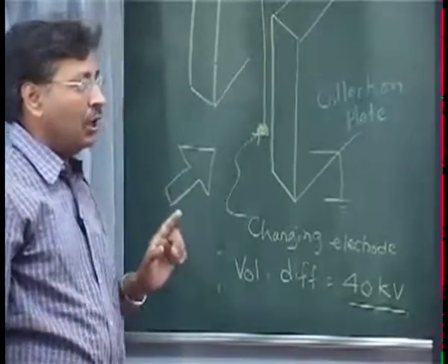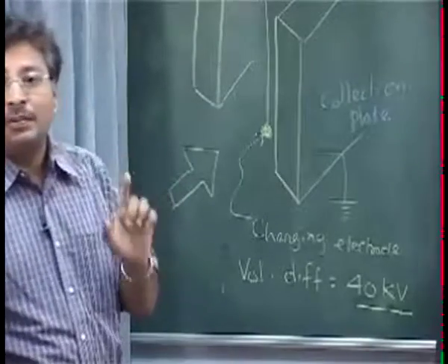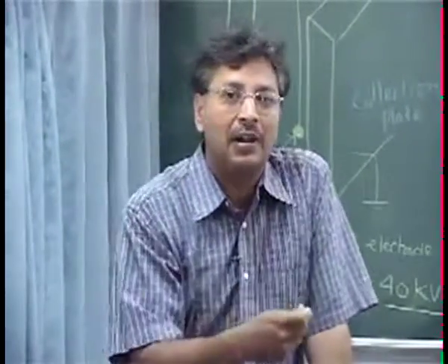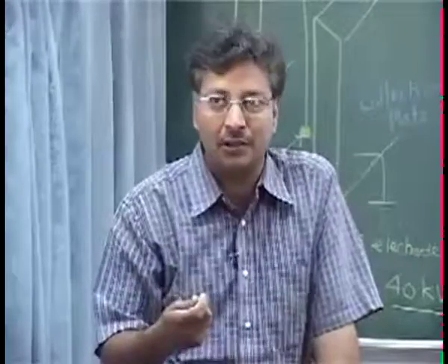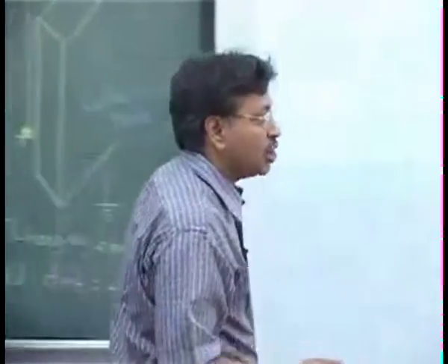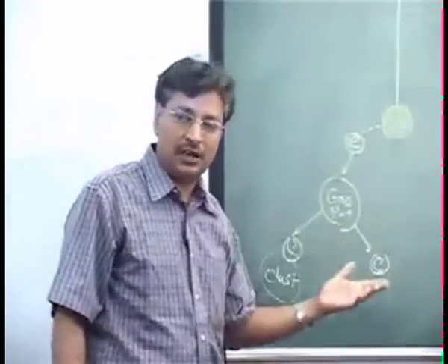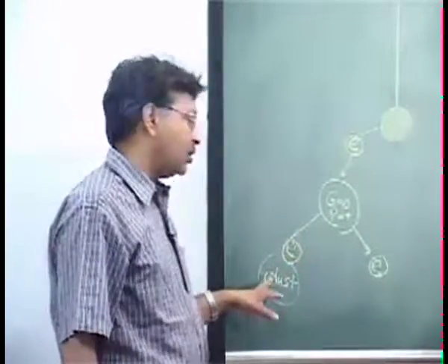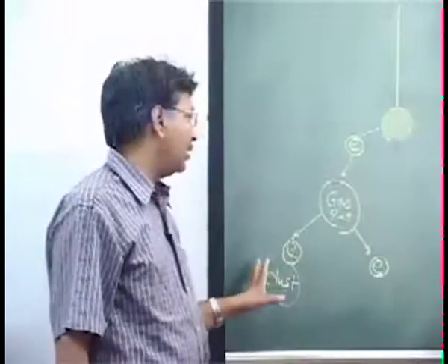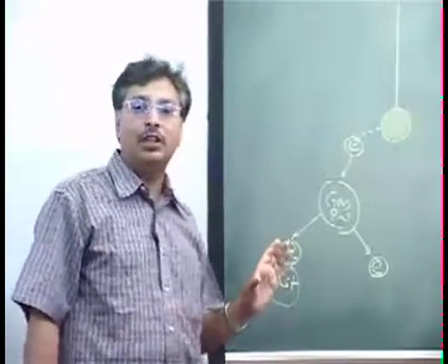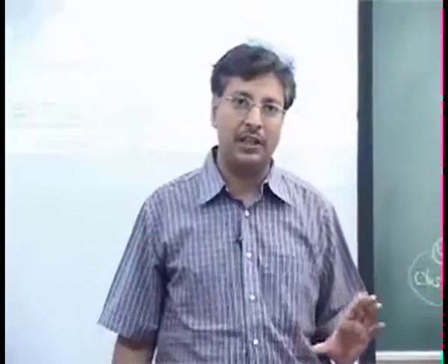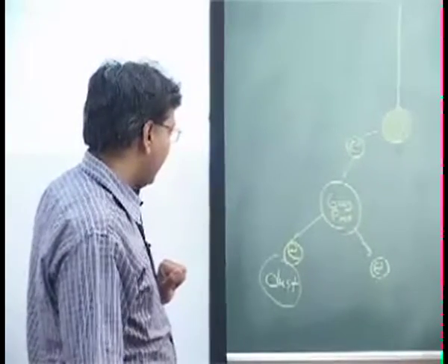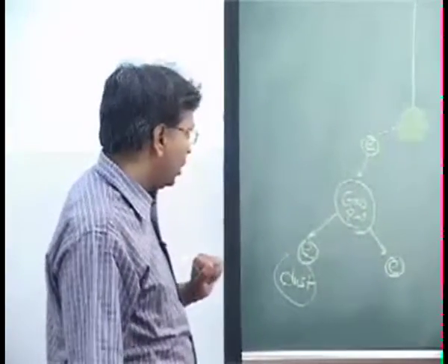So remember that ionization is taking place only for gases, because sometimes people get confused. They think the electrons hit the solid or dust particles and the particles become charged, and ask where the electrons are coming from. But that's not the case. The thing which is getting charged is the gas, which is generally the air, or the flue gas. More electrons come out, and these electrons sit onto the dust particles, and then these particles continue to travel because of the charge they are carrying towards the collection plate, and sit onto the collection plate. Okay. So is that part clear?